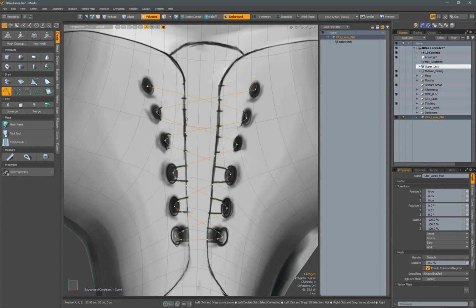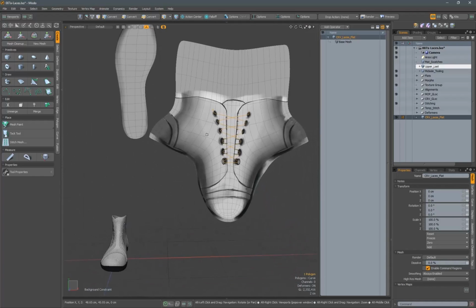All right, now that we have all of these verts placed, let's go back to the beginning. The reason we're doing this one last is because it functions a little differently when adding points to the very first one, because they're always added after that first one. So what we want to do is place another vert where the one goes in, then do the one after, and then move the original one to the position of the one going in. Now that we have the curve all set up for this, we can drop the tool with the space bar.